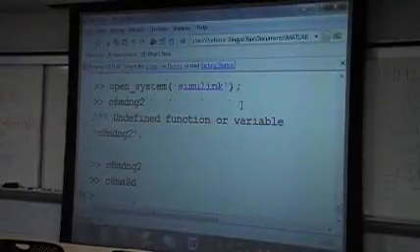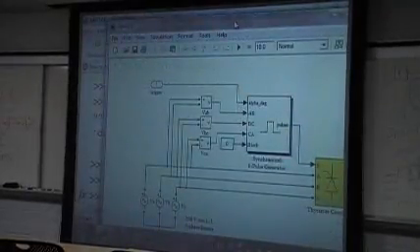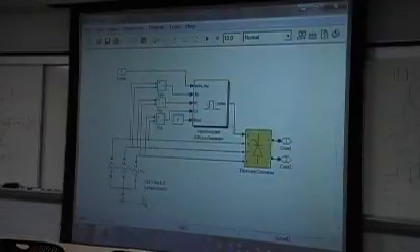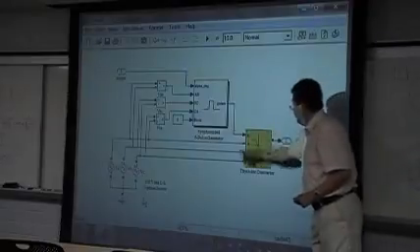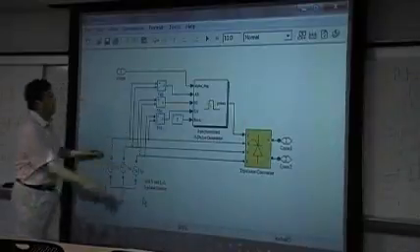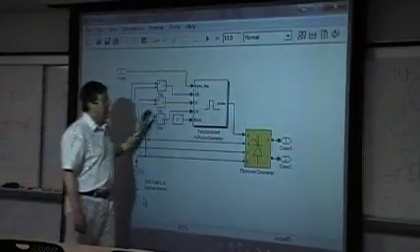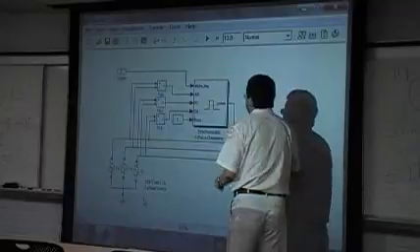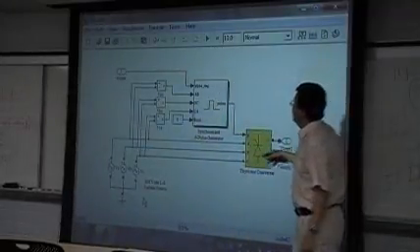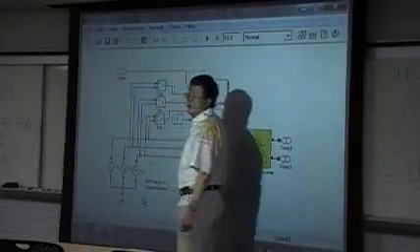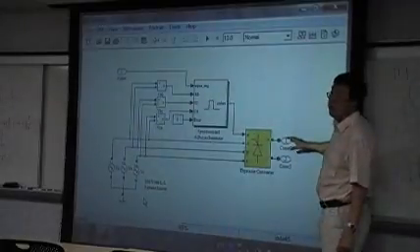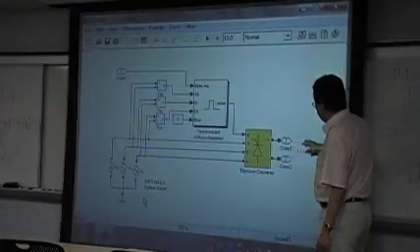This is the model I created earlier. And in this model, this is a key component. And we have a three-phase input here. And then we can connect the three-phase input and also the pulse generator to this one. And this one will give the trigger angle. And then we should have a DC output like this. So we can display the final result. Also, we can connect it to a load.